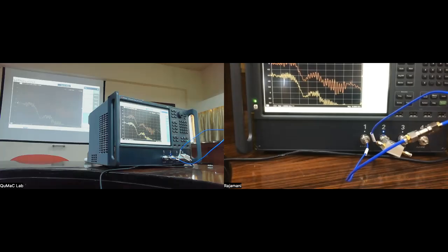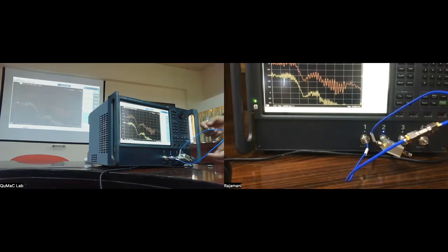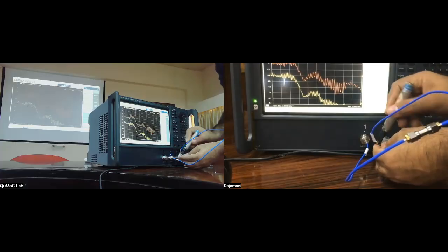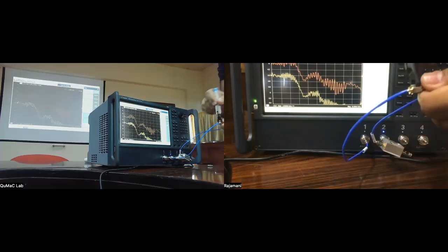This typically happens when you take long cables. If you even just look at a coaxial cable of different lengths and you look at the patterns in the reflected signal, then you will see that they will get closer and closer as you increase the length of the cable. So the interference, because now we are having multiple reflections, so it's happening that way. Let me put this back.